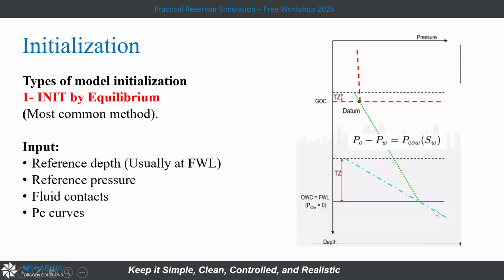With this gradient, with support from the well logs, we can confirm that it's a water gradient. For example, if the water saturation or the resistivity log tells me it's a low resistivity formation, and the pressure has this gradient, then it's water. And in this oil zone, we'll have this gradient. As I mentioned, the oil gradient could be 0.35, and in gas it will be like that.